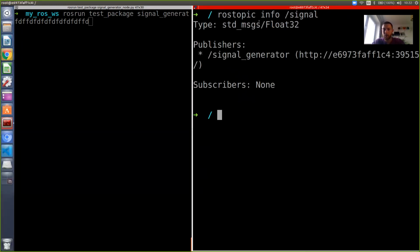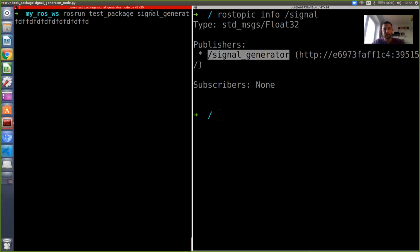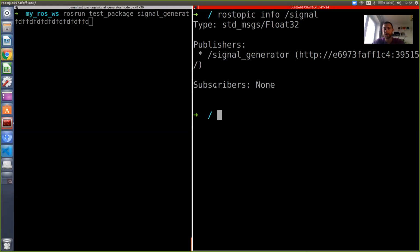We see that this topic has a specific type, std_msgs/Float32. And you remember that our package depends on std_msgs. So everything is correct. And we see that the publisher is some signal generator, which has some particular address. But for us, it's important that this is a signal generator. So this is the name of this node. And there is no subscriber because nobody reads this topic.